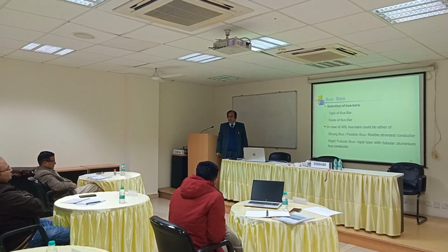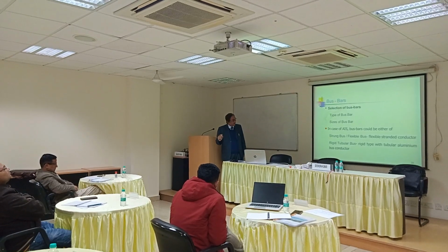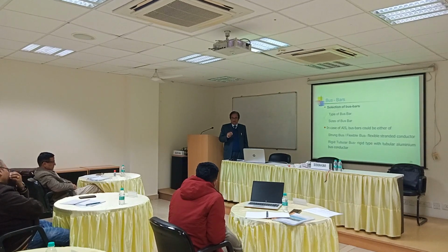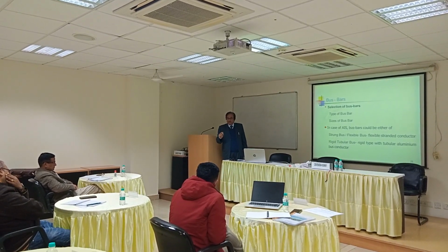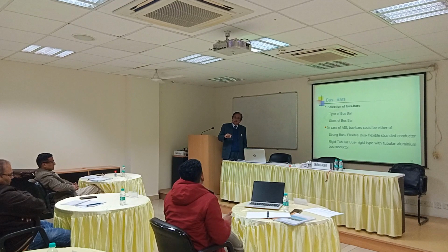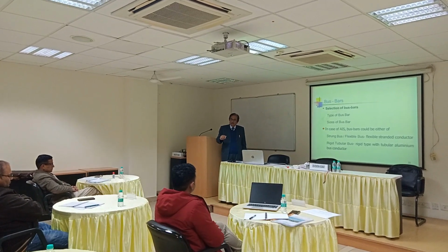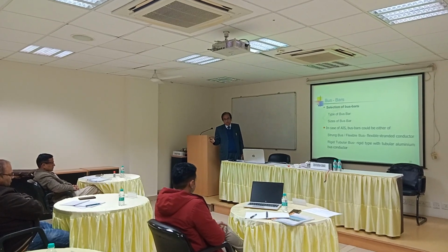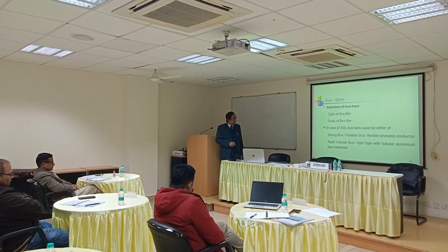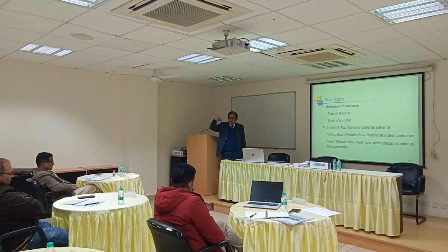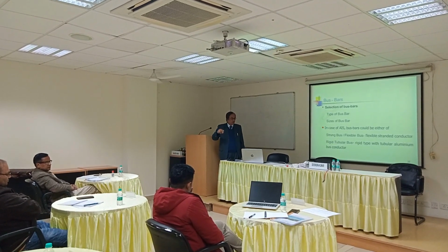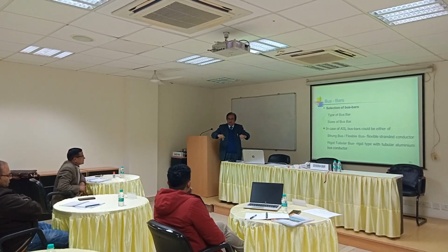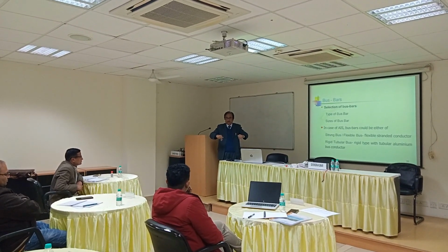In this particular bus, flexible stranded conductor is used, and we do the stranding of the conductor only to increase its flexibility. So this strung bus or flexible bus is suspended from the gantry, you can say.